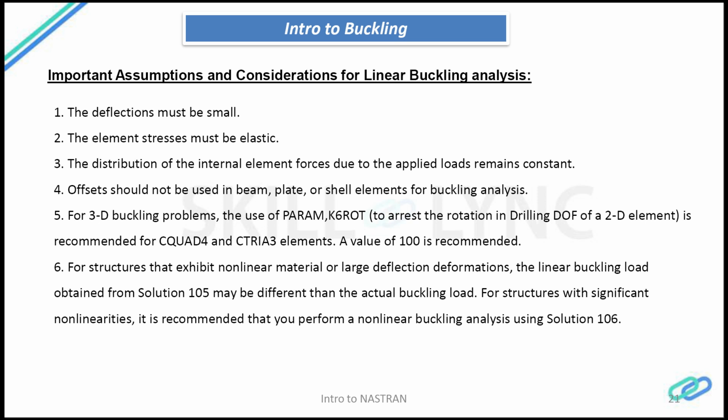Or suppose you directly run the buckling analysis and you're not seeing the results you are expecting, then it is clearly understood that you have to run the model first for the nonlinear analysis before you attempt the buckling analysis. First run the nonlinear analysis, see how the results vary, what kind of deflections you get, and what kind of things you get.